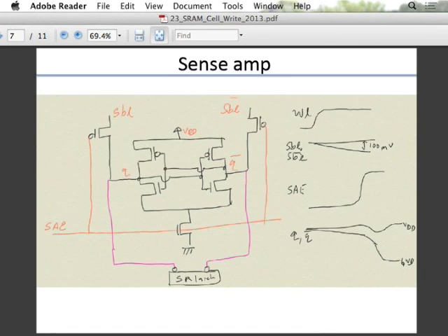So this is the sense amplifier which is used pretty much now in all memories, SRAMs and DRAMs, and probably other memories also. This is what is called a clocked sense amplifier. Let's see how this sense amplifier works. It looks like a memory cell. Basically, there are two cross-coupled inverters, except this node, instead of being ground, is connected to ground through this NMOS device. SBL bar comes in, and there are also these two PMOSs here. SenseAmp enable is initially low. That means these two PMOSs are on, and initially both Q and Q bar are at VDD before you do the read.